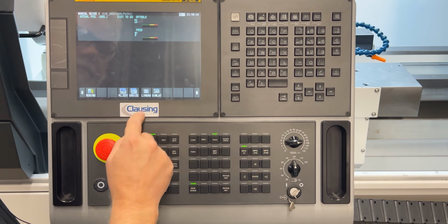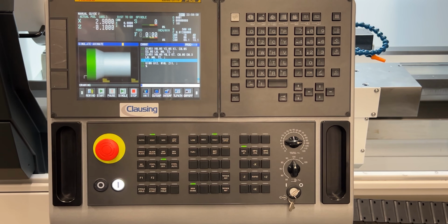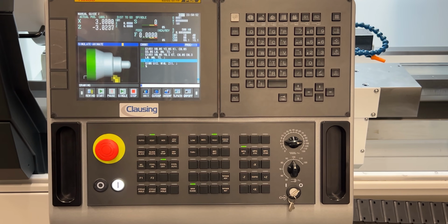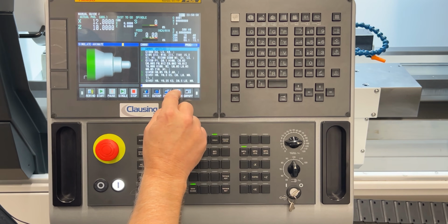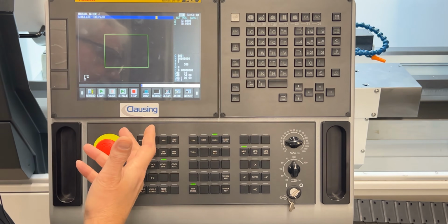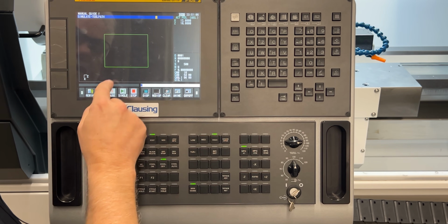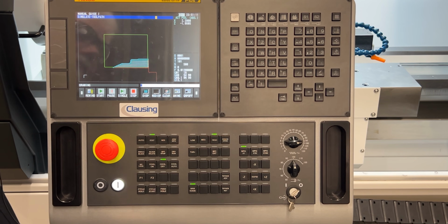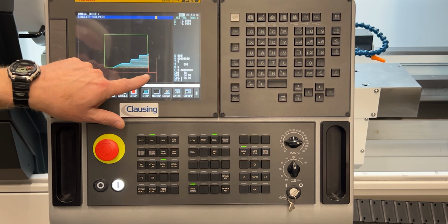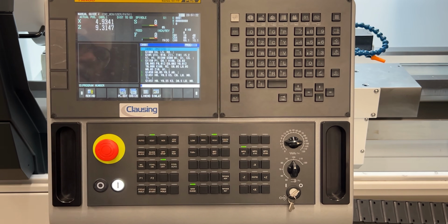Let's go to simulate and start. And I do want you to always go to toolpath, because the solid graphics doesn't necessarily show you a good ID visual. So anything that's on the ID, you definitely will see in here. If I do the line graphics, if I see any red lines in this part of the drawing, then I've got a problem. And then when I'm done, I just hit graphics off.